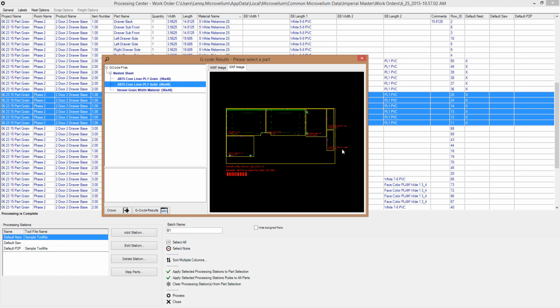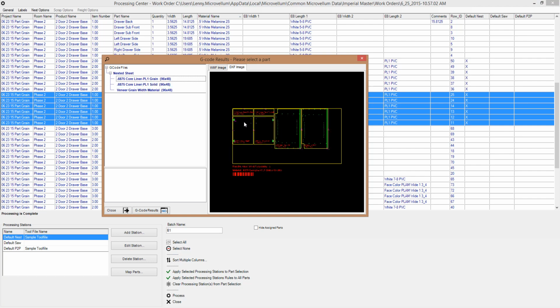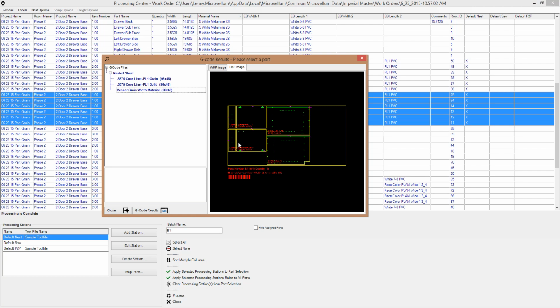So the non-grain material, same thing. Cabinet 1 just does the same. So now cabinet 2, vertical grain length sheet, and it's turned them that way, and then these are turned that way. So the end result is the parts will end up being appropriately grained. So this previously, in order to do this, we would, especially for drawer fronts, we had that option to vertical grain or horizontal grain the drawer front.